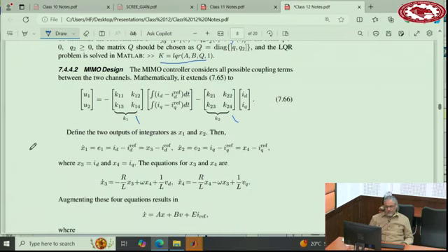So if you really look at the equations and define the state variables properly, let's define x1 and x2 as the state variables of the output of the integrators. Therefore, derivatives of these state variables become the tracking errors, right? So you can put it here, and ID and IQ will be x3 and x4. So we have 4 state variables, but together now.